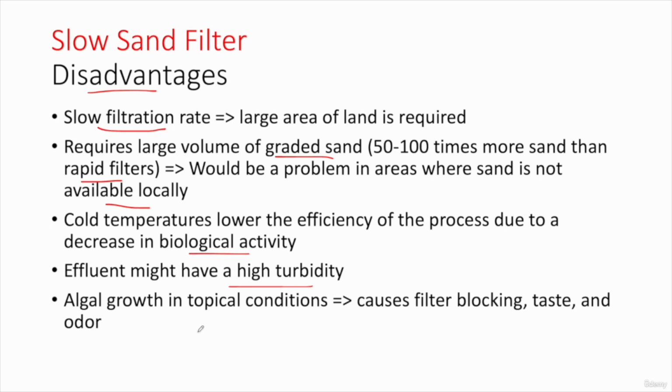Also, we might face algal growth in tropical conditions. These filters are exposed to atmospheric conditions. They are exposed to hot weather, to sun. So this can cause the algae growth, actually, and this might block the filter and cause taste and odor.